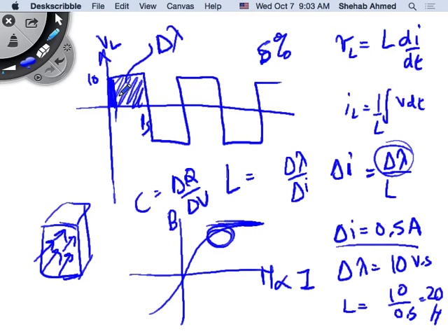They're not operating at high frequency. He's trying to push the limits and operate at megahertz type frequencies, right? So then he's going to be able to use capacitors. He's going to be able to use the printed circuit board as a capacitor. He can use the printed circuit board as an inductor. Just draw some wires in the printed circuit board, and it will be an inductor. He just needs a small value of inductance. He doesn't even need a core.